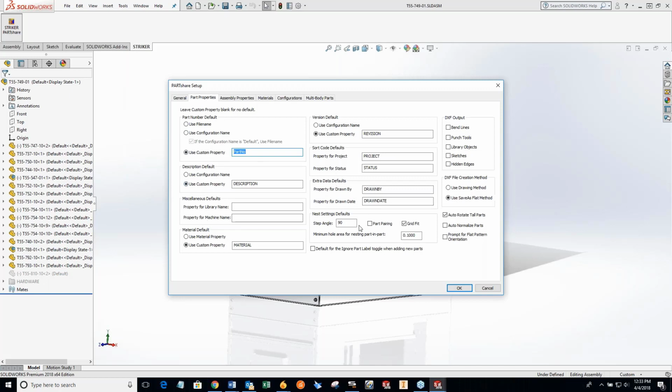Okay, so if you're doing just a save as DXF out of SOLIDWORKS or Inventor, and then bringing that into your part library, because you're going to be manufacturing that, laying it out in a nest or what have you, you would have to re-enter all of that data: re-enter the part number, re-enter the machine information, the material information. Of course, we know anytime you start re-entering data, you're introducing a potential that something's going to be miskeyed.